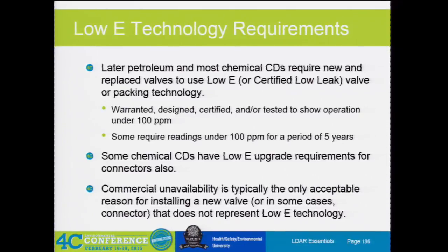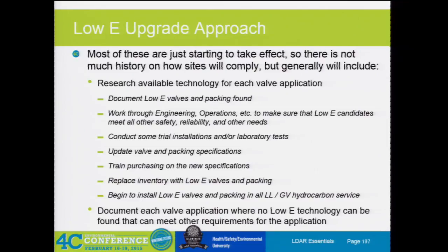The last piece is, like David was talking earlier, ball valves. Well, I don't know of any ball valves that are out there that are meeting the low E requirements. So they're commercially unavailable. And each one in each CD has a little bit different writing for what you have to prove that it's commercially unavailable. But that's something, if you guys are ever interested in, we've put a lot of data together that kind of shows what vendors are out there that can meet these requirements and which ones are starting to come into the requirements, just to help everybody kind of stay ahead of the game.